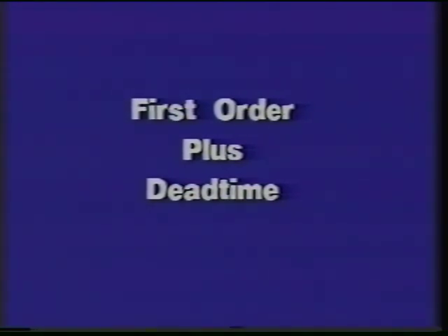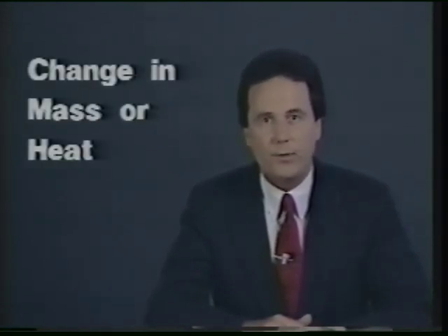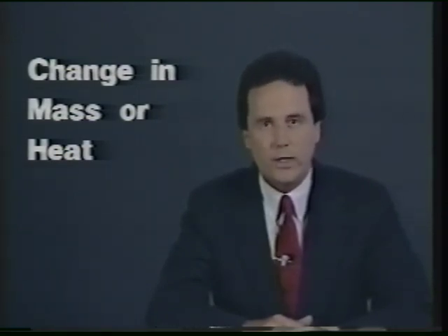You can think of these as a pure delay process, followed by a pure lag process. The reason that this characterization is accurate in so many cases is that so many processes naturally involve the transfer of mass, or heat, or both. This means that there is a certain length of time required for the change in heat or mass to move through a pipe or other medium of exchange to the location of the process. At this point, there is a time requirement for the full effect of the change to develop.